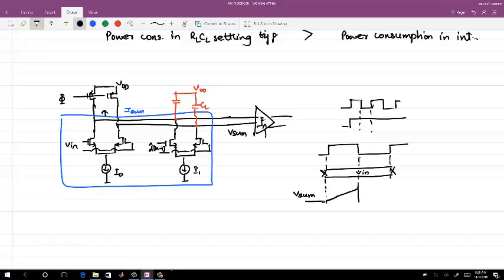Okay, and then this is the on phase, this is the off phase, and in the reset phase I bring it back to 0. That is how I can deal with it without one bit spilling into the other one. But what did this implementation do here? Whatever I have talked about, I am integrating the input voltage for 1 bit period. But because I cannot integrate enough without resetting, I have to reset it.